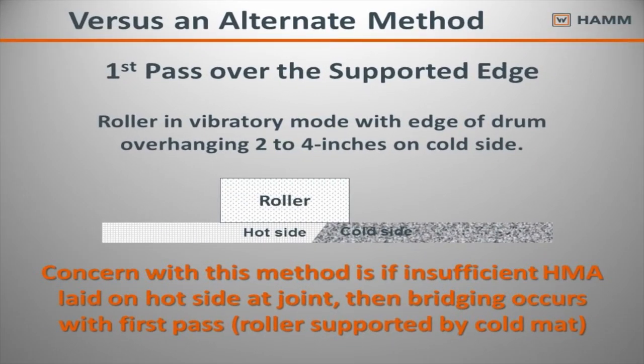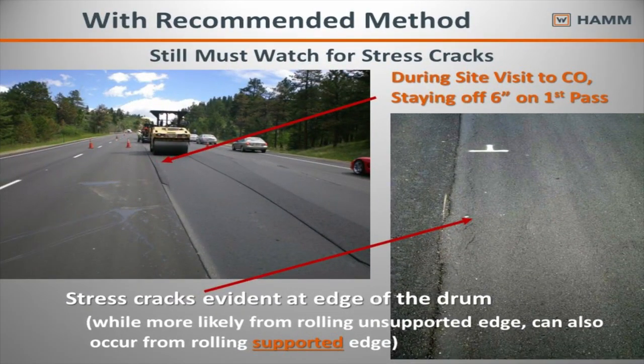Here again, on the hot side, we're going to bridge here, but we're going to pinch point that drum there. Now you got all this material in here that's not going to get compacted. Not to the level we want to. Same thing, we can even do that push out on the joint, so we have to be careful. Every mix is a little bit different in how it's going to react.